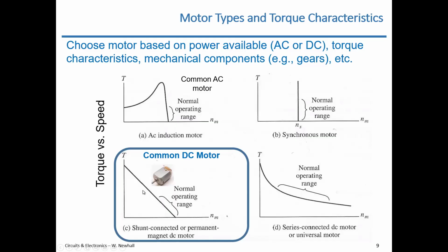So the way this works is that if you were to let the motor free run and not apply any external torque, that would be as fast as you could get that motor to turn. That would be the no load speed. You're applying zero external torque to that shaft. It has some friction inside, there's some internal torque, but I'm talking about external torque applied to the shaft. So that's letting the motor free run.